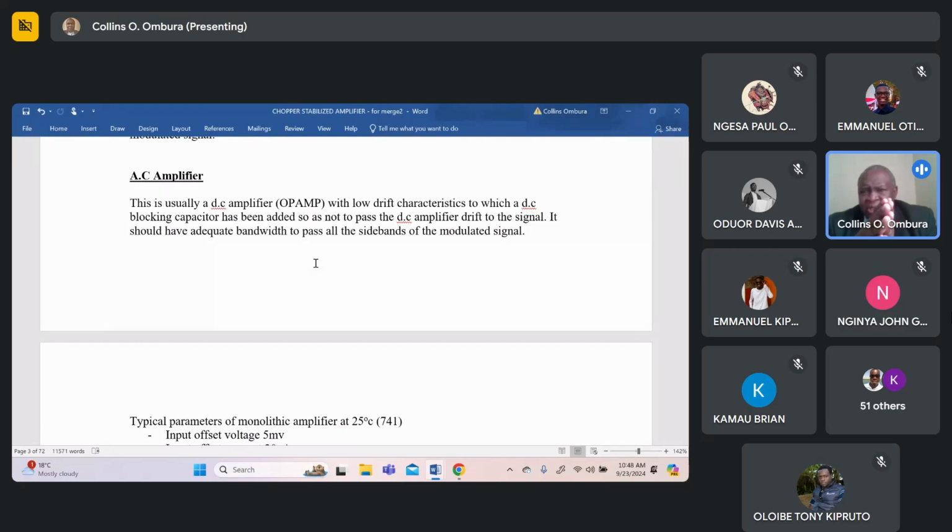And there are government bodies in most countries that regulate how much emission is allowed from power supplies. So you find that they're shielded. If you've broken open one of your laptop power supplies, we call them maybe power bricks or adapters, you'll find that they're shielded. But if you break open, say, your mobile phone charger, there's no screening. It also uses a switch mode power supply, and it uses MOSFETs inside there. There'll be very little radiation from it.